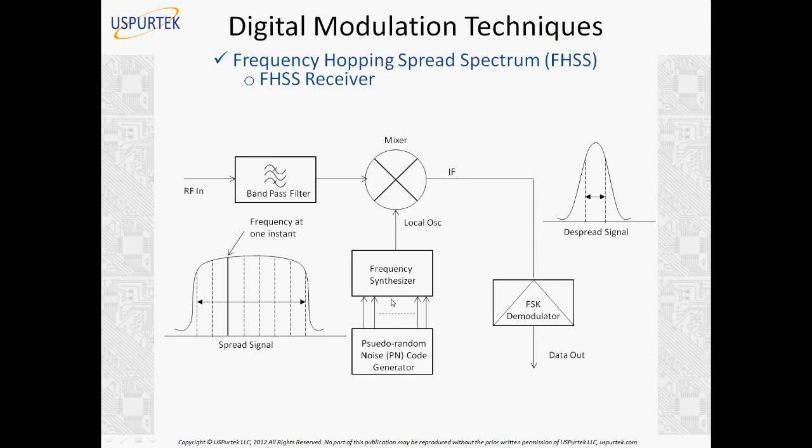That is why we cannot use QAM with FHSS. We have to use frequency shift keying or multiple level frequency shift keying or things like that. We cannot use QAM because phase coherence is not maintained when we hop frequency. So that is why FHSS does not find use in CDMA techniques or any other spectrum techniques.